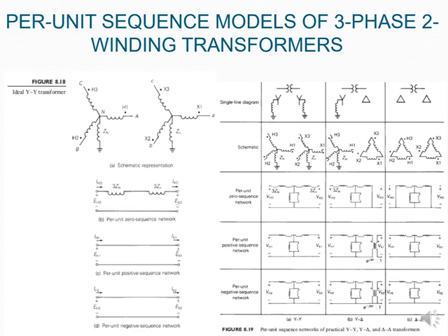Then this shows you, in the number of connections, what you can be expecting to have written onto your system. The first ones are your single line diagrams, how they would show up. And the next one is schematically how you could draw this, and then at the bottom of those we split them up into our zero, our positive, and our negative phase sequence.